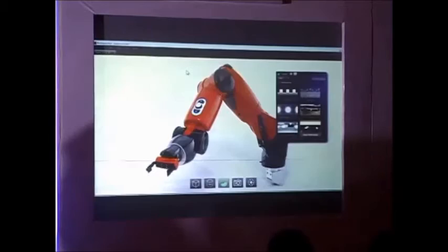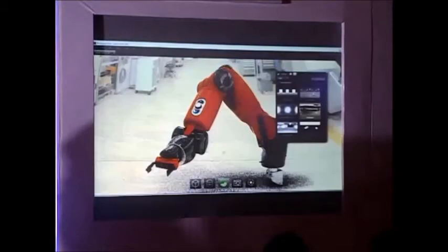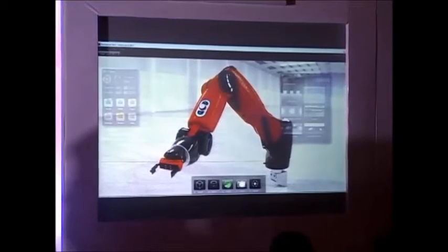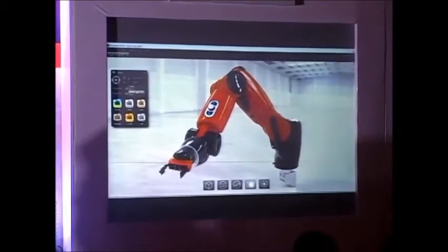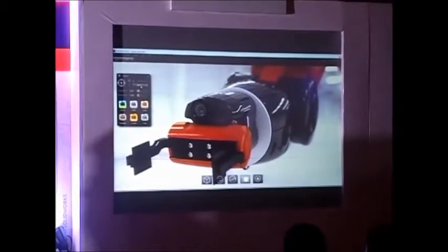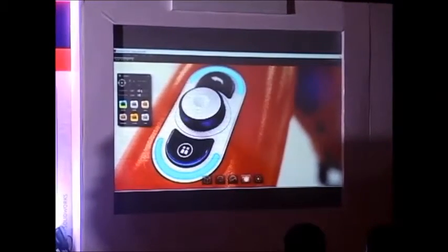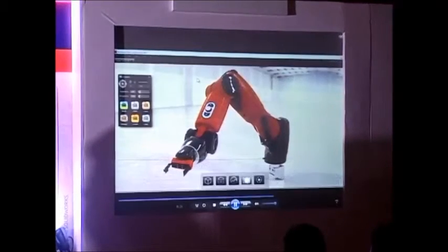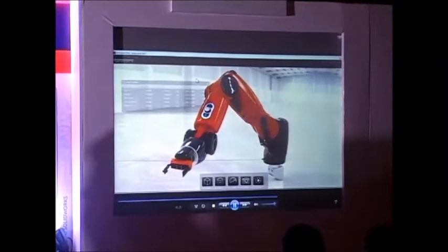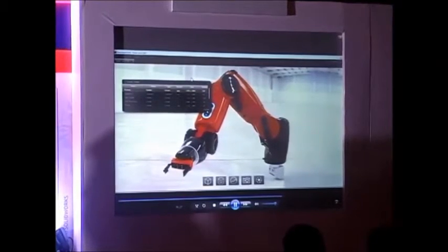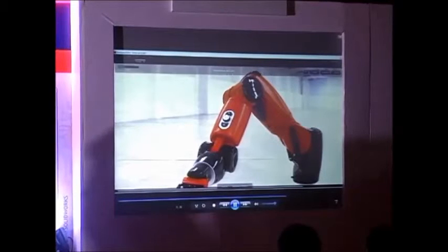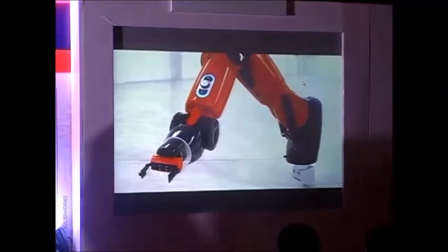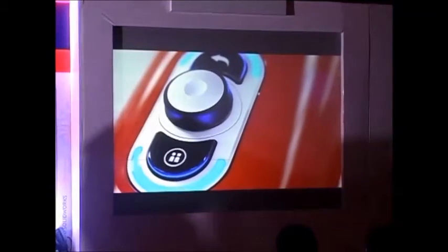Environments can be easily applied by dragging and dropping onto the viewport. This environment can be dynamically dragged and positioned to get good shadow effects. And multiple cameras can be used for innovation and newly generated ideas. By adjusting the filter, we can set camera resolutions. By clicking final render, it will provide you the estimated time in which the images will be ready, and a pause button is also available there. So these are some of the render images which have been created using SOLIDWORKS Visualize.